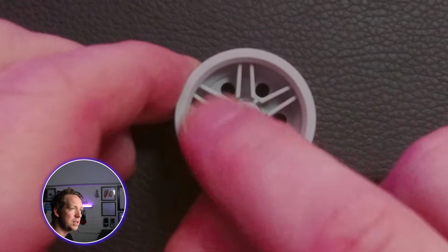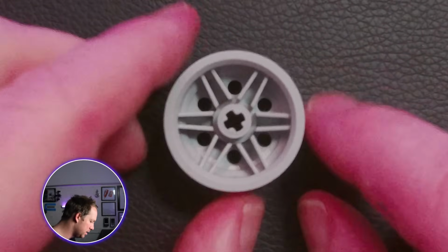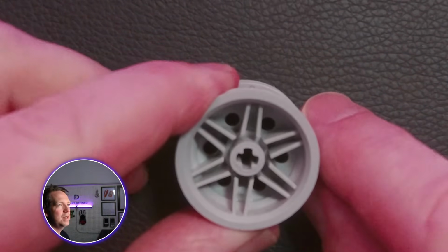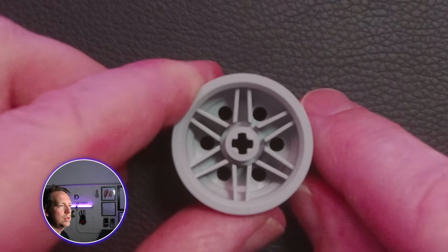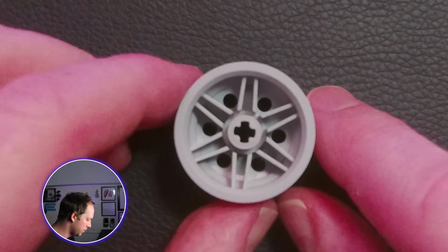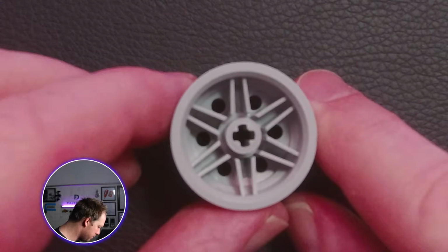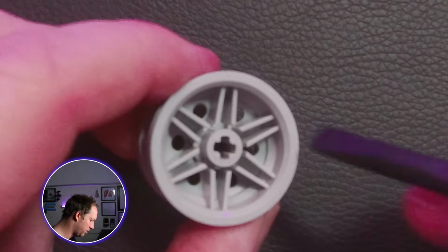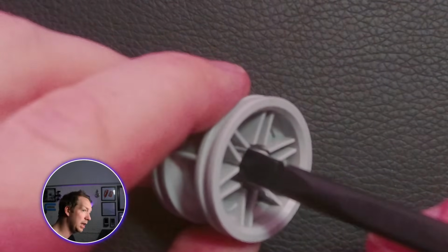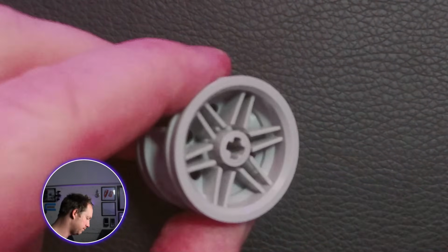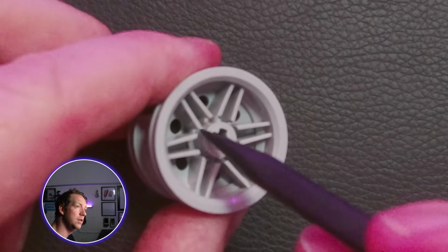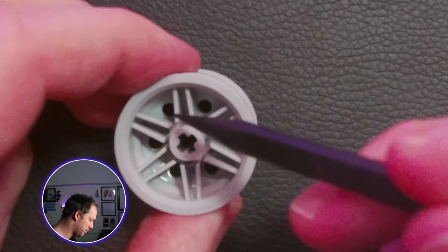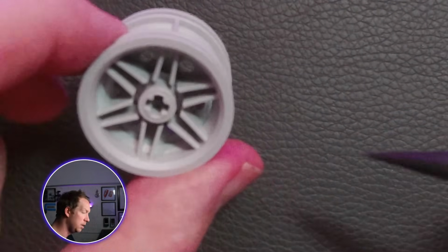It's going to be difficult to measure some of this internal detail, but most of it is patterned. So we'll be using some circular pattern features. Interestingly, you can see on these features here that they're not complete ribs, like there's a gap here where I can stick that tool. So yeah, they're kind of spokes, but not quite.